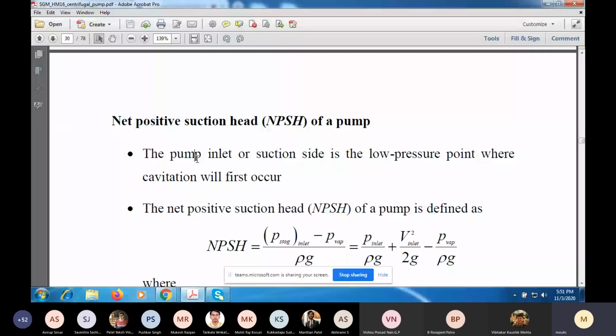Now the pump is increasing the pressure, so the maximum pressure will be at the outlet of the pump. So just at the exit of the pump or the inlet to the discharge pipe, you will have the maximum pressure. And as the fluid flows through the discharge pipe, the pressure will drop due to friction along the pipe.